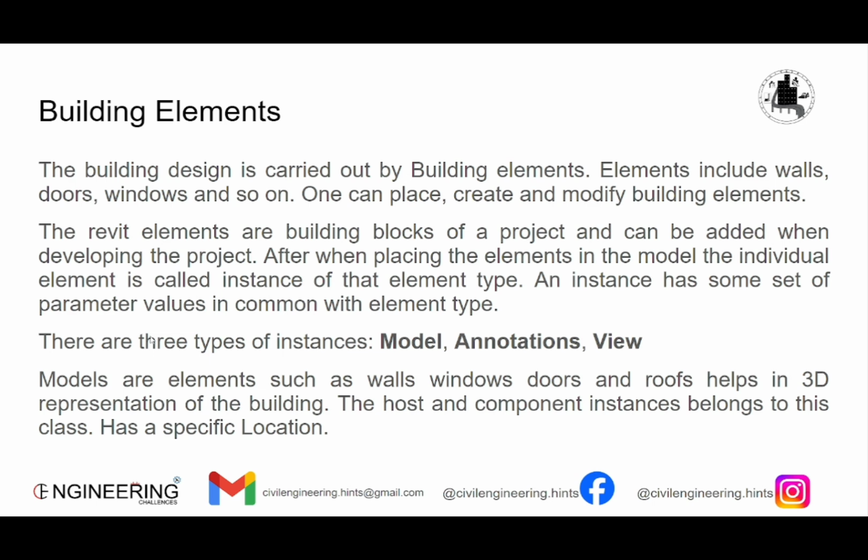If we see the definition of building elements, REVIT building elements are the building blocks of a project and can be added when developing the project. When an element is placed in a model, the individual element is called an instance of that element type. An instance has some parameter values in common with the element type.